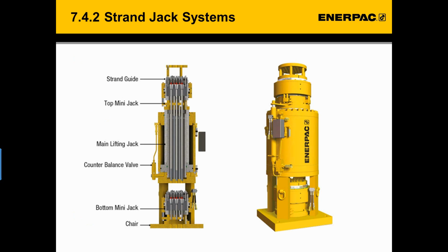It is good to understand how a strand jack actually works. Let us look at the main parts and then watch an animation which will show you the normally invisible movements inside the strand jack. As you can see in the image, strands are guided through the jack with the help of strand guides, which help to keep the strands at a set distance from each other to avoid tangling.